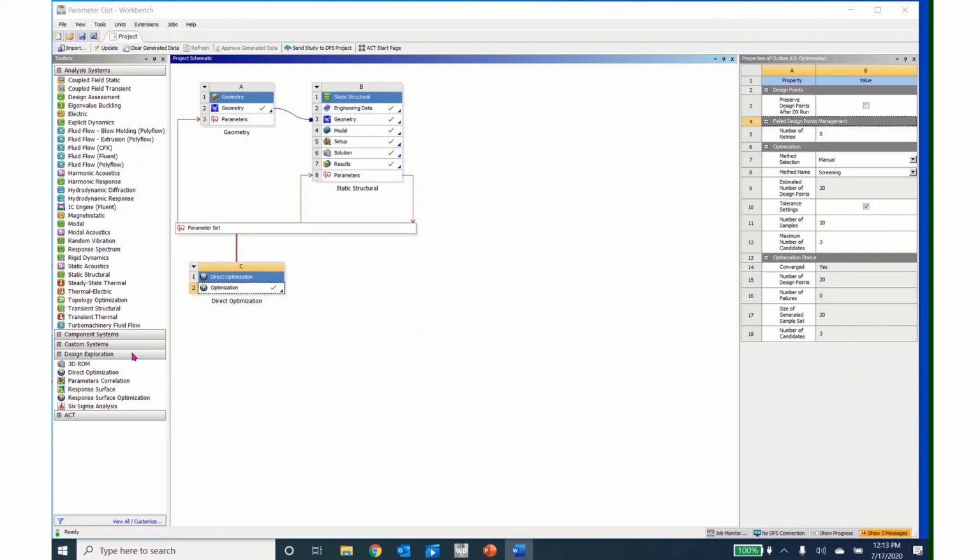Ansys Workbench uses the Design Exploration tool to do a parametric optimization. This toolbox has various ways to look at design correlation data and results. The general steps for doing a parametric optimization consist of starting with a what-if analysis. This is a best guess approach, and it can use Ansys generated data or manually entered data to perform the analysis. We then move to the correlation studies, where we assess what actually matters to the output.